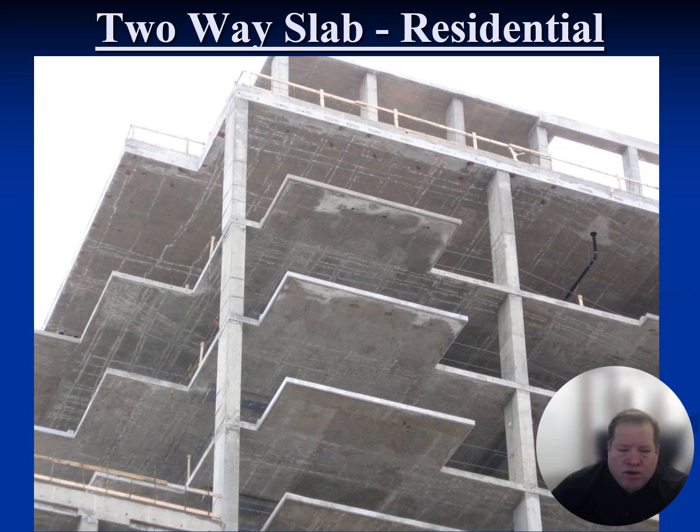This is a residential structure that was done a few years ago back east by a friend of ours. And you can see here, a two-way flat plate slab. The nice thing about this photograph is that there's an undulating slab edge, which again, for hotels, for apartments, you're going to have balconies and stuff like that. Nothing you can't do with PT or with a flat plate. Obviously, these are cantilevers over here and cantilevers on that side.